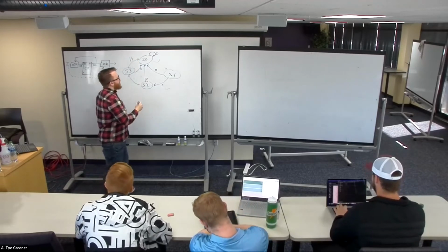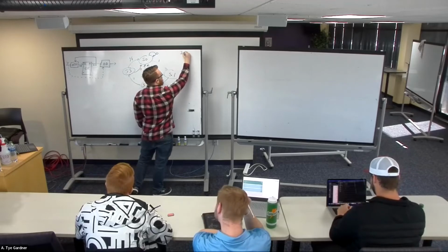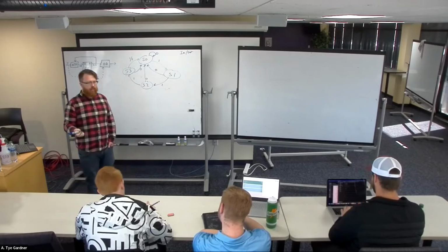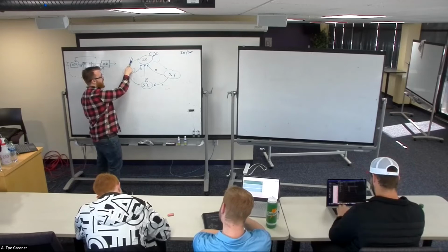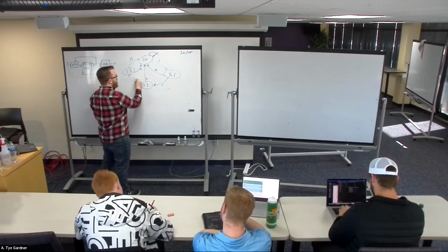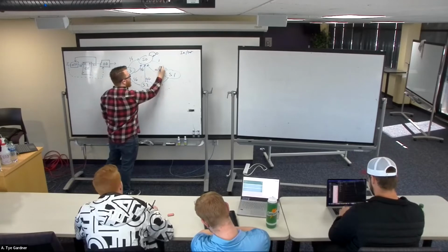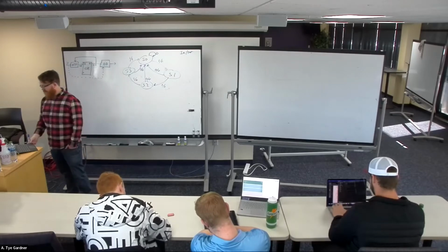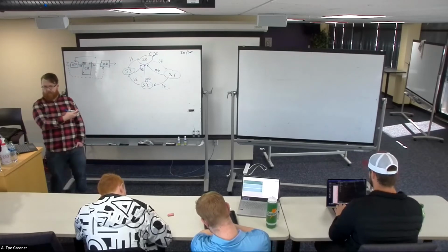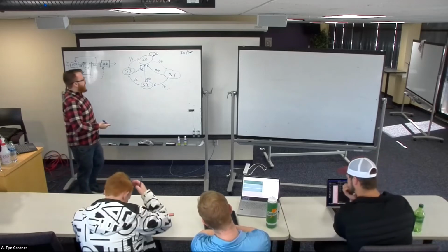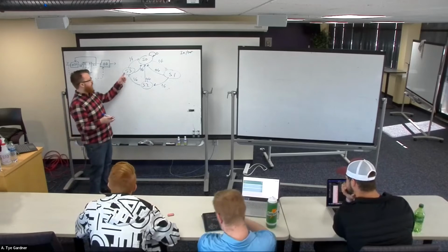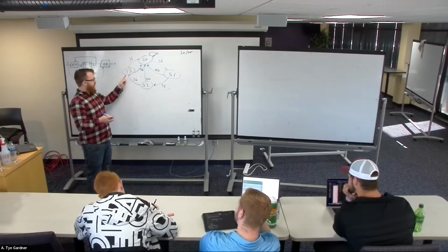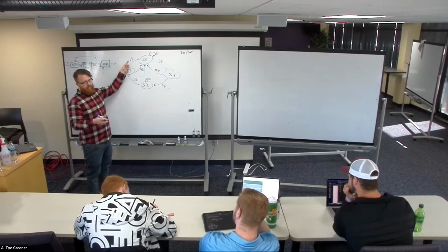So this is the in/out Mealy style transition notation, right? This is saying if I get a 1, the output is 1 and I go to state 0. The rest of these are dash zeros, meaning the output is 0 in any other case. This makes it really quite easy to deal with this type of output decoder, right? We could look at it, and if we didn't really care about complete minimization, we could just say if I'm in state 3 and I get a 1, then my output is 1. So it's just an AND gate that is state 3 and 1, right?